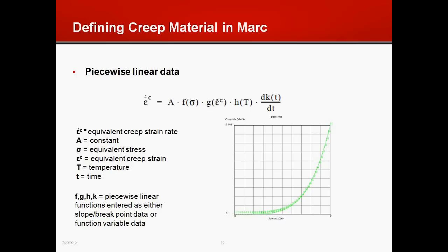On the other hand, if you have the creep strain rate as a function of both stress and temperature, you can read that as well, except that you would now need to have multidimensional tables in a specific format that the Marc GUI requires. So if you format it in that manner, you can definitely read the information back into Mentat. But notice that when you have these tables in multiple dimensions, it can get a little bit tricky to visualize the information. And if you have a curve fitting program, it might make things a bit simpler if you actually go ahead and perform the curve fitting operation.